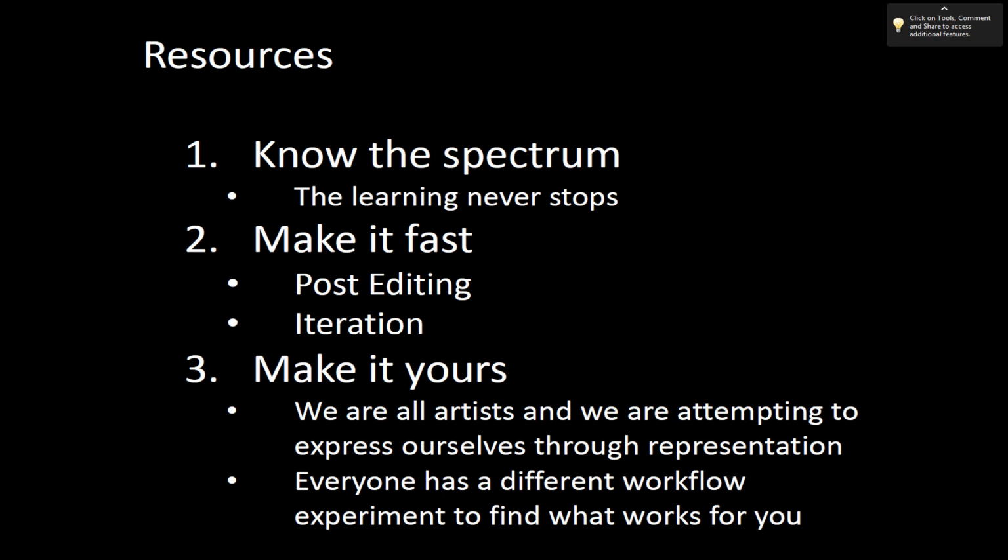But the number two thing for me is to make it fast. Use post-editing to your advantage and allow it to be fast enough to iterate on your ideas, because otherwise if you're spending 6 hours per rendering or something like this, it gets overwhelming, and you're just not able to produce as much in the end and use it to your advantage as a designer. And so I limit myself, for example, to half an hour for the rendering, and then post-editing can be another half an hour, and that way I can iterate on my ideas.